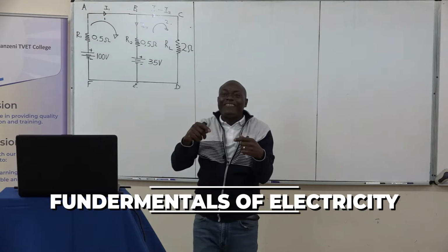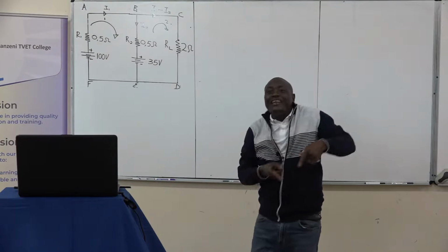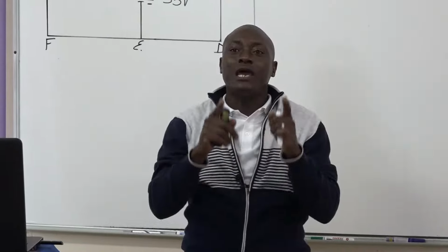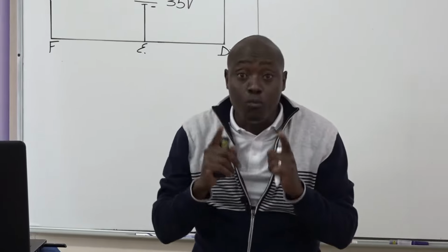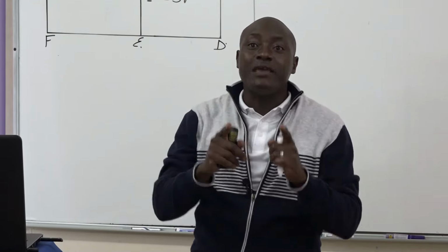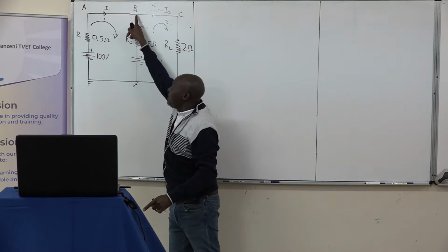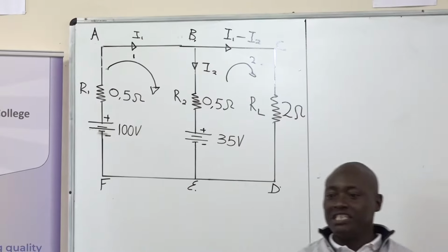It's going to force another current to change its direction. So to avoid that, because it's going to be more complicated, make sure that if you've been given a loop that you're supposed to select, you select the current that is flowing in the same direction.